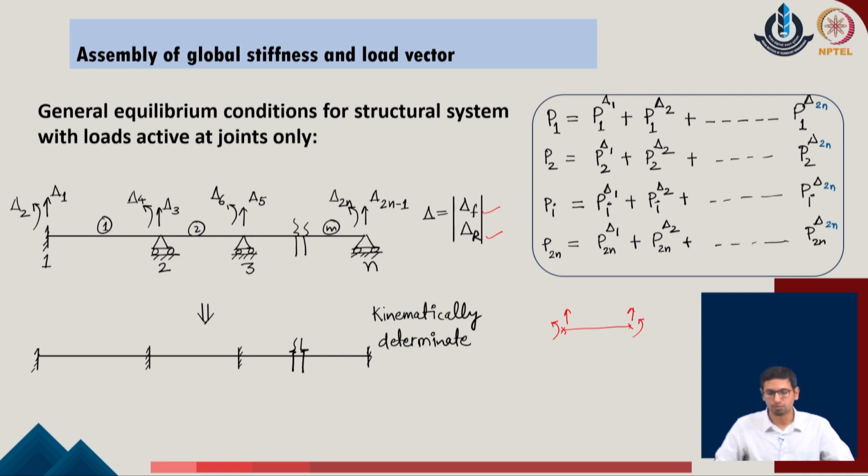So, when we talk about simple beam cases which are non-deformable, we add two components of the deformations, one the transverse deformation and the second the rotation about the normal to the given plane, and those two values are added at both the ends of the given system. So, both the joints attributed to the given member will be contributing these two components of the degrees of freedom at each of the joints, and this way we generate a member based stiffness matrix which is of the size 4 cross 4.